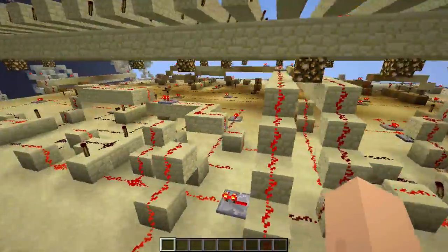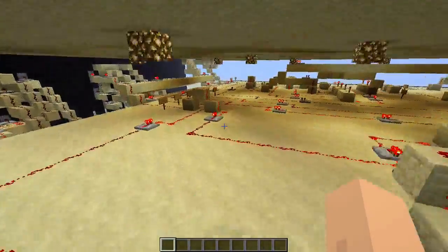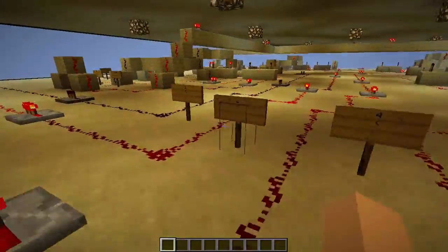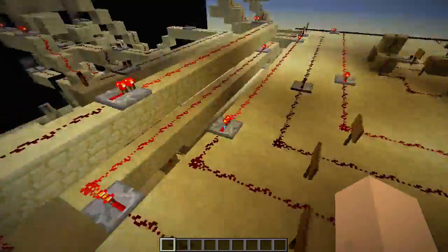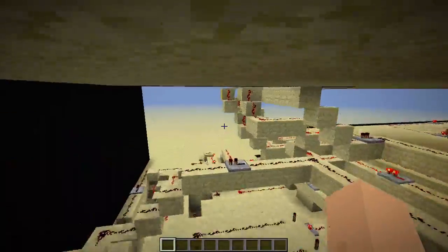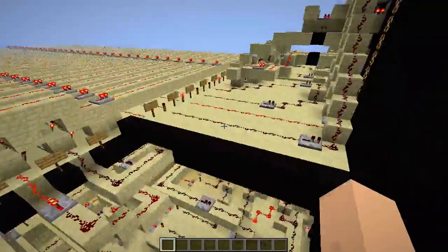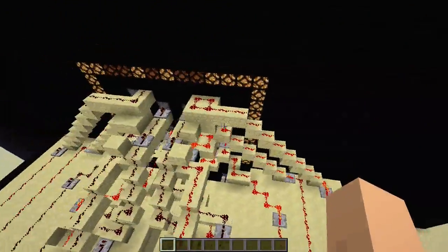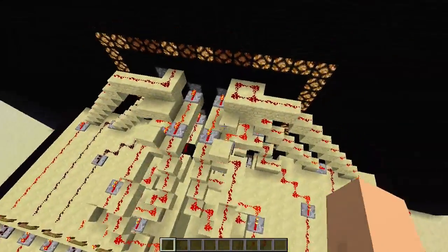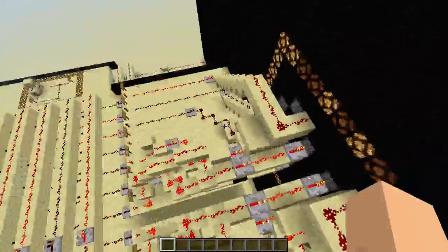And now onto the top part. As you can see, I'll show you quickly. Here's the 5-bit output, 1, 2, 4, 8, and 16, and these 5 bits then go to the top section. The top section is the 7-segment decoder for the top 2 displays. So we've got 2 7-segment displays at the top. This is actually simply a mirror image on each side, which is fine.